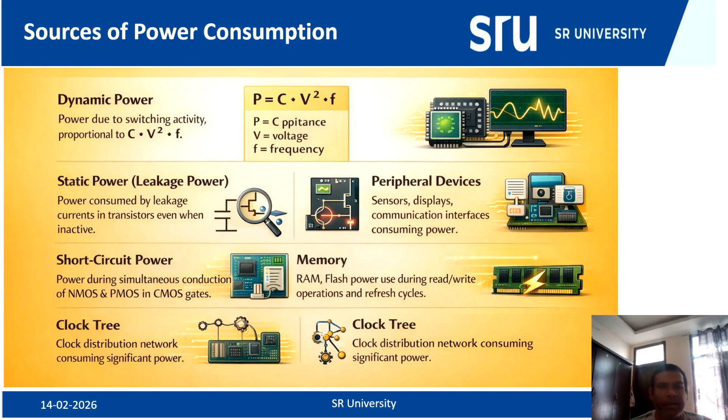Another contributor is short circuit power, which occurs during brief transitions when both NMOS and PMOS transistors in CMOS conduct simultaneously. Although this happens for a very short duration, frequent switching can make this component noticeable.